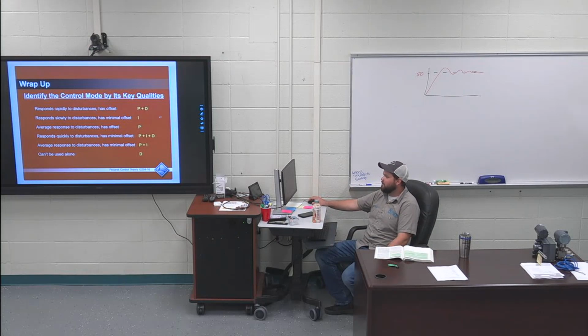The derivative actually helps it respond faster to disturbances. PID responds quickly to disturbances and has minimal offset. Average response to disturbances, minimal offset is PI. Can't be used alone is derivative. Kind of makes sense?